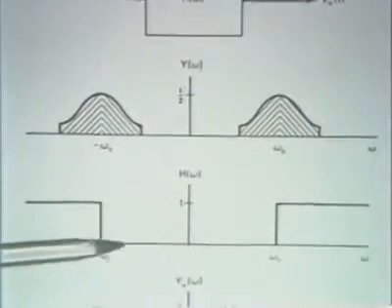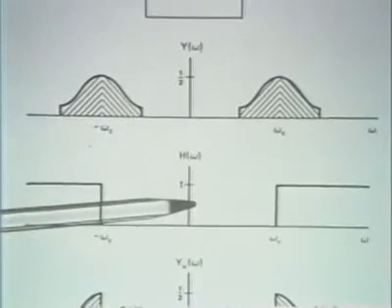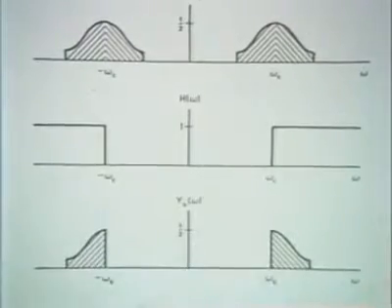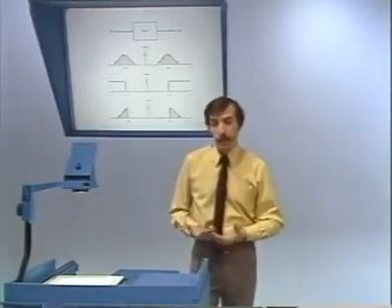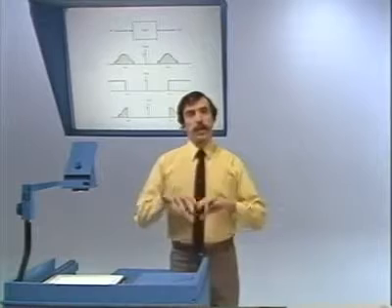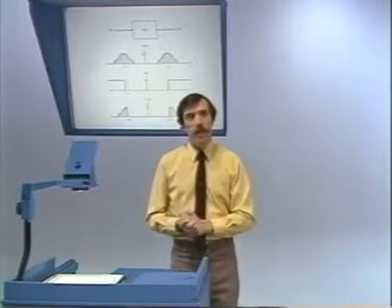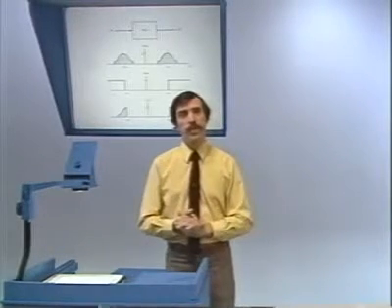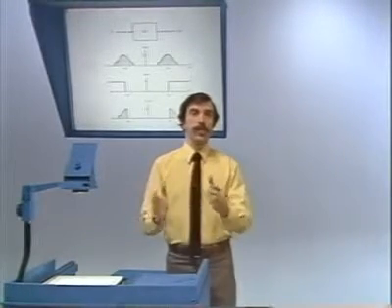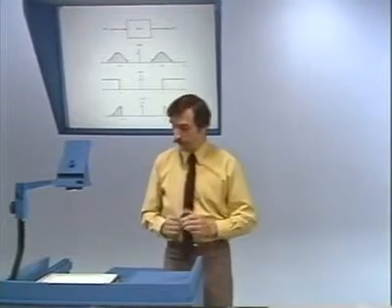So this, of course, conceptually is a very sharp cutoff filter, and what it eliminates are the lower sidebands, and the resulting spectrum is what we have below. And this, in fact, is really the basic idea behind single sideband transmission. Again, there's a trade-off. It's clearly more efficient than double sideband transmission, but it also has the complication that the modulator becomes a little more complicated, because you need this filtering operation or some equivalent operation to get rid of the unwanted sideband.